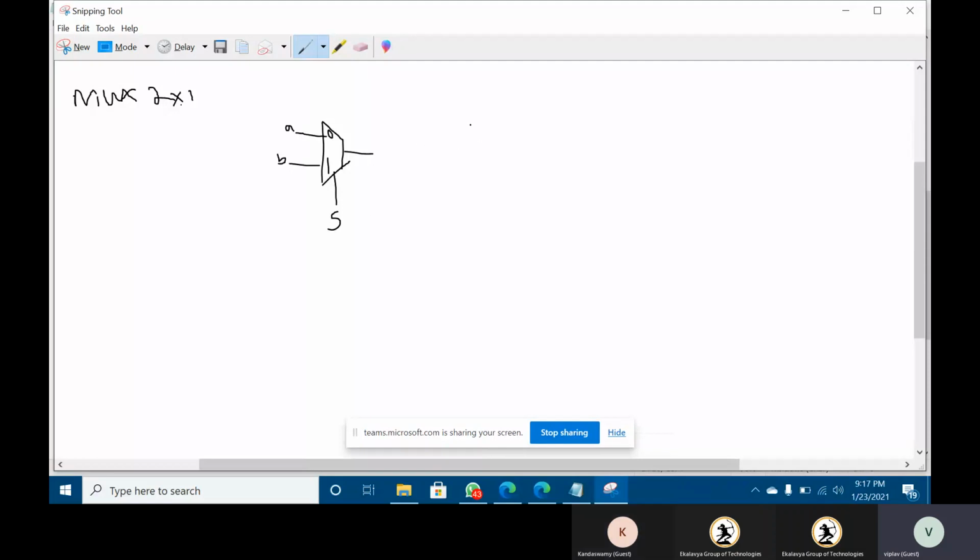So what I am doing in GDI, by the help of this mux idea itself, first thing I am going to do is take one PMOS. Then another thing, I am going to take one NMOS. One PMOS and one NMOS. By taking the idea of mux, what we are going to implement is the GDI AND gate, means AND logic by using the GDI technique.